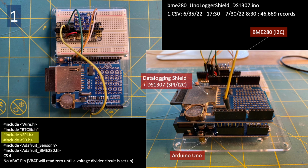All the data loggers I tested communicate using SPI, and thus always reference the SPI and SD.h library. And because we're using SPI, we need to define a chip select or CS pin, as is done here, set to 4 for this particular hardware combination. CS pins may vary by microcontroller and data logging shield, so care needs to be taken when selecting the same, or the microcontroller won't be able to communicate with its data logger.